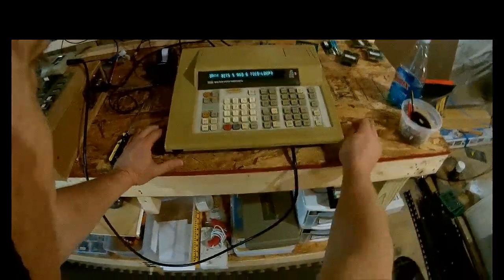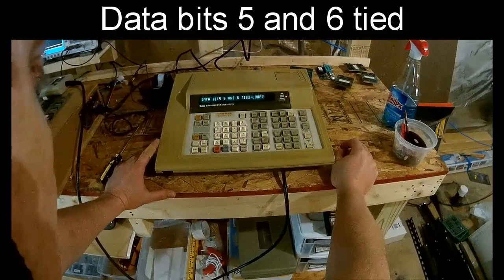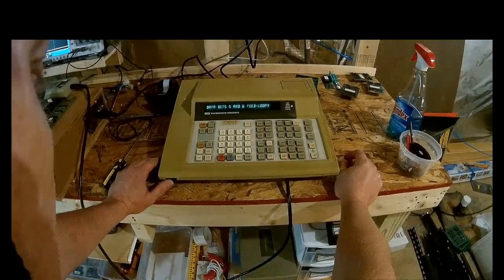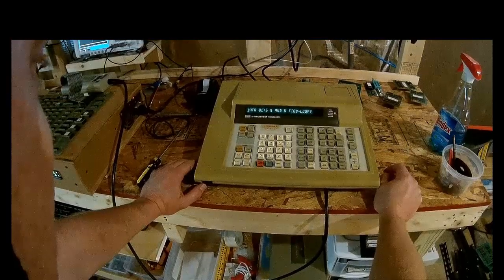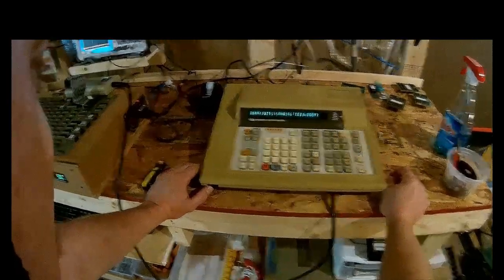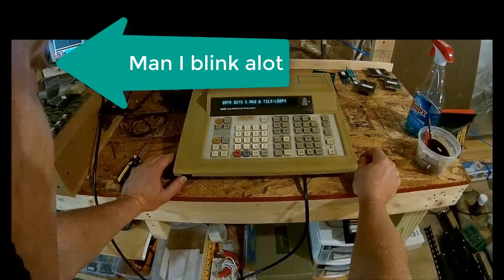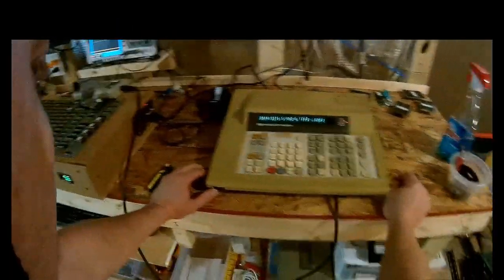We do a bus test, and we see immediately data bits 5 and 6 tied loop. Now, this is very rare that you see this, because there's usually not many chips that directly can talk to the CPU. Usually only some buffer chips. And they're the first chip that the CPU sees. So this is clearly a problem. If the data bits 5 and 6 are tied, nothing's going to work. All right, so we have to figure out why that is.